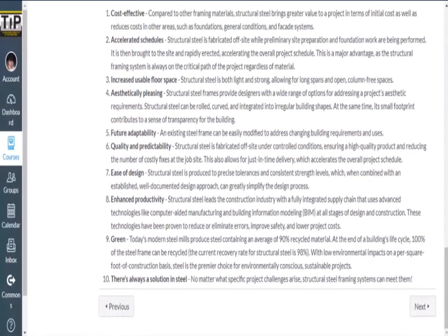Unlike in concrete, for example, if you demolish a concrete structure, you can only recover and recycle the aggregates. The cement paste, no? You cannot recycle it anymore, so it will be left as dust. No? So it would harm the environment more than steel. Okay? Although in reinforced concrete, you can still recover and recycle the steel bars, the reinforcements. You can still recycle them.